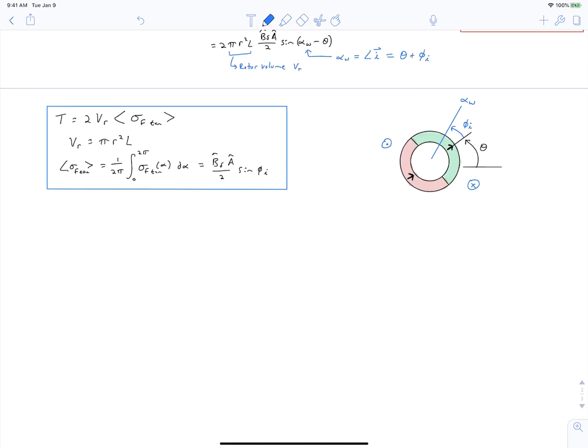And let's take this a little bit further and talk about our current space vector for torque. So we can break our space vector up in terms of d and q axis currents in the conventional way. That is, we have these d and q axis currents that are rotated by our rotor angle. And the argument of these currents is phi, which is the arctan of this quantity. I just forgot the arctan here. So the arctangent of IQ divided by ID gives you the angle of this component right here. And that determines this angle right here.